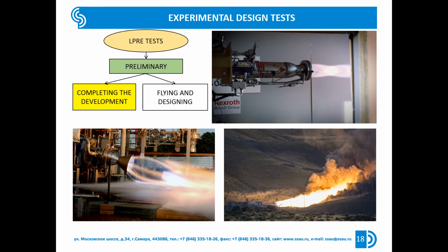Reliability can be evaluated from the results of all tests performed on an LPRE that has a final design of the main elements. At the same time, a significant number of tests are required to quantify the reliability of a liquid propellant rocket engine. Time and cost savings can be achieved by performing multiple tests on a limited number of liquid propellant rocket engines, increasing their continuous operation time and weighting the modes. The methodology of the final development tests is very similar to that of the weighted mode development tests and the adverse combination of external and internal factors tests.